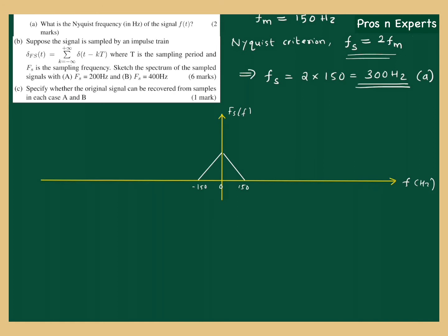This spectrum gets repeated infinitely to both sides, positive as well as negative sides. Okay, this is what you are going to encounter when this signal with this spectrum was sampled. An infinite replica of the same spectrum is obtained on both sides. Now how often does it repeat? How often it repeats is denoted by the sampling frequency.